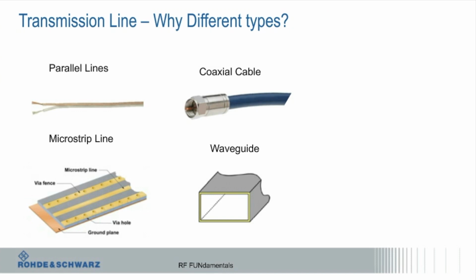I like PAs. Okay, so anyways, microstrip line, that's a transmission line on a board, and there are different variants of that. That's a single transmission line by itself, but then you can also have what's called a coplanar waveguide, which is a similar thing where the ground planes are more closely defined to maintain that and reduce the fringing effects.